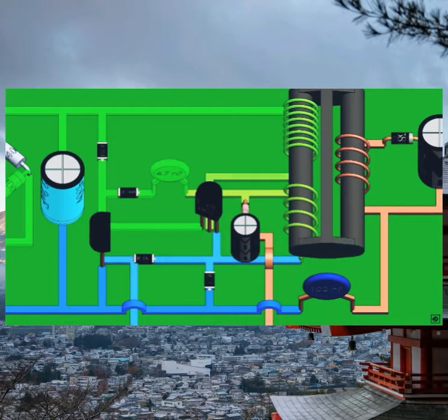As the transistor is now fully on, it allows the current to flow through itself. Now, this turns on the transistor T2. This shunts the base of T1, turning it off. As T1 turns off, the flow of current to T2 is cut off. Now the current flows to the base of T1 and the cycle repeats. This happens at 15 to 50 kHz, which is 1,000 times faster than the rectifier circuit. Hence, you would see that the rectifier circuit appears stopped.